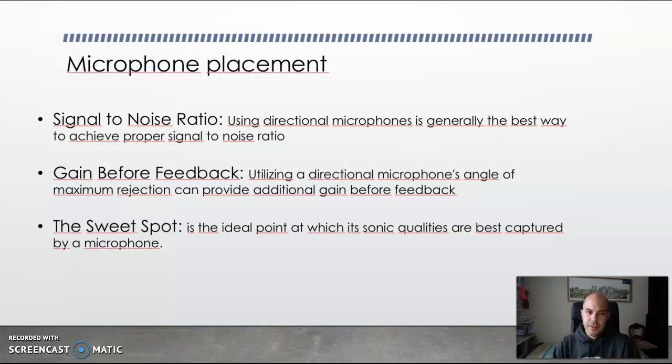So when we place a microphone, we are looking for signal-to-noise ratio. Using directional microphones is generally the best way to achieve proper signal-to-noise ratio. It means that between signal and noise, we prefer signal. Okay, and we need to avoid noise.